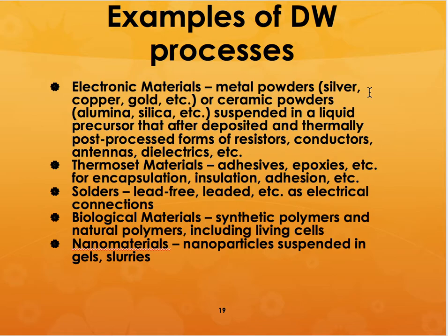Of course, the most common one are the different kinds of nanomaterials. You know that when you add nanomaterials to different kinds of binders and different kinds of carriers, the viscosity is going to go through the roof. So direct write is one technology that can allow you to deposit these materials very easily.